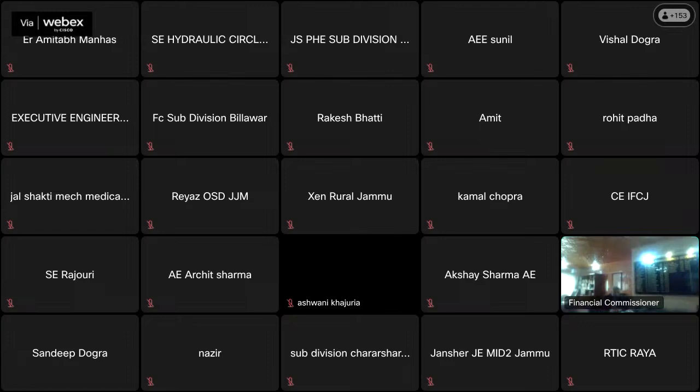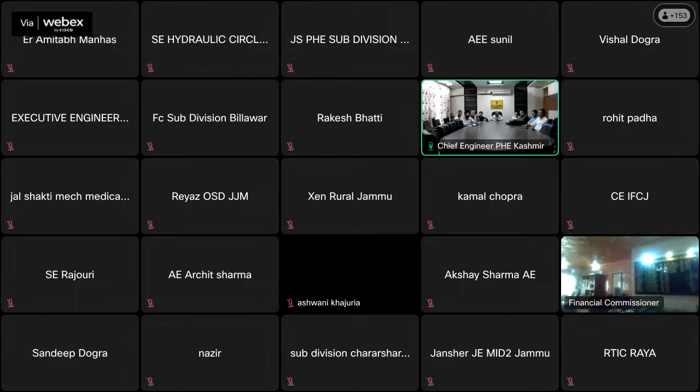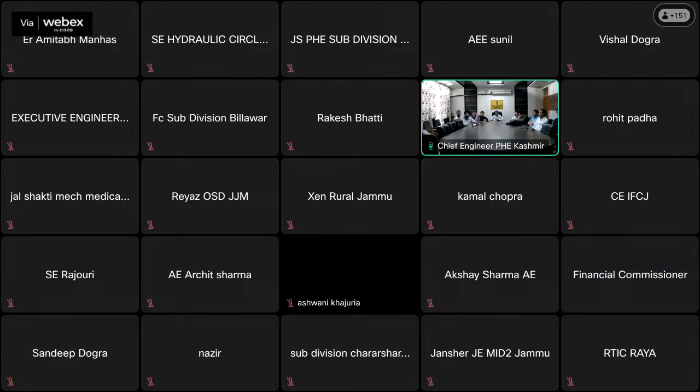Mr. BP Singh, would you like to comment? Yes, sir. The question the gentleman raised: the schedule is very much followed during the maintenance of these DG sets which are used in the power house system, and mostly the pumps are in the drinking water system. The pumps mostly remain submerged in the water, and mostly the damage occurs to the bearings. Generally, sealed bearings are used, so no proper or scheduled greasing is maintained for them. So the replacement is there only.